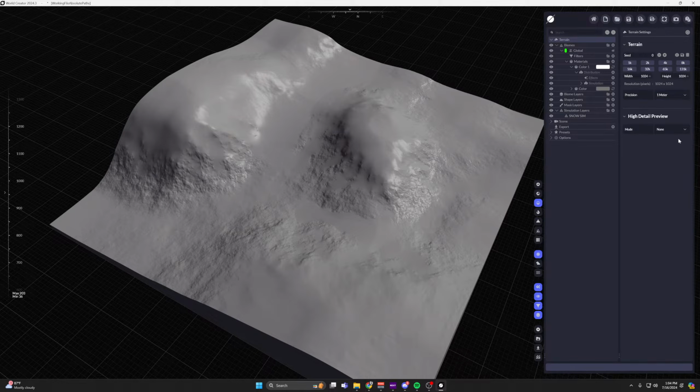Whatever you do in here is to scale, but say you want to assume that this is twice the size that it is, you can export this at 1 kilometer by 1 kilometer and still decide to put it in another application and scale it however you want. If you want the height of this, right now it says 150 meters. If you want that to be 300 meters in another application, just multiply the Z factor by 2 and you'll get 300 meters. So there's a lot of custom control that you can really do.